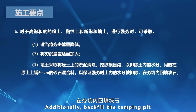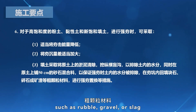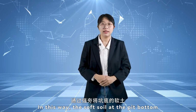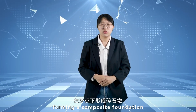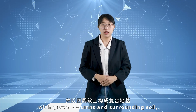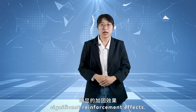Additionally, backfill the tamping pit with coarse materials such as rubble, gravel, or slag to achieve displacement compaction. In this way, the soft soil at the pit bottom is squeezed outward, forming a composite foundation with gravel columns and the surrounding soil, which usually achieves significant reinforcement effects.